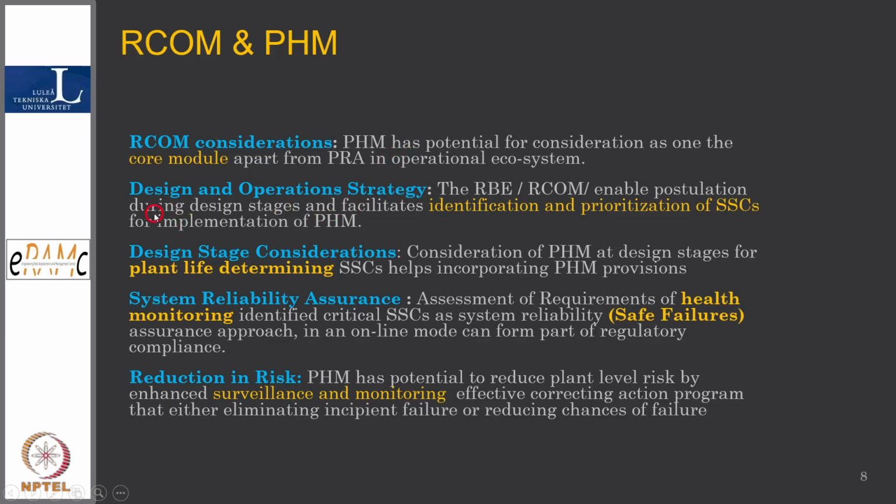And when we talk about design, if we have PHM during the design stage itself, of course, even now provisions are made for life limiting components. Provisions are made to see their degradation in terms of corrosion, erosion, and many other degradation mechanisms. But if we do it with these advanced methods, the limiting life will be identified a priori, and whether at regulatory level or at plant level, there will be a comfort level.